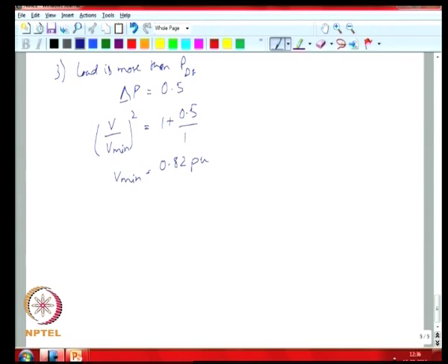Okay. So, in this case, suppose you have a relay which was looking at under voltage, and you set your under voltage relay to 85%, then it would disconnect the DG, because the DG would be seeing an under voltage in this case.